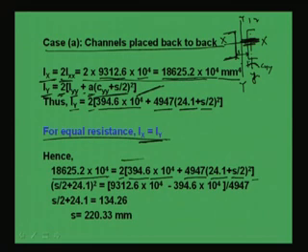This is Iyy and this is Ixx, right. Now, if we make them equal, then what we will get? That S by 2 plus 24.1 whole square will be equal to 9312.6 into 10 to the 4 minus 394.6 into 10 to the 4, by 4947.